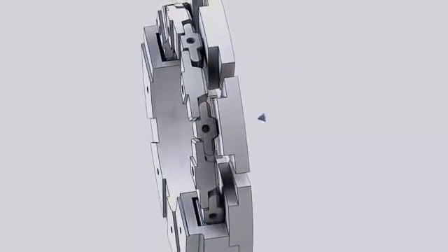The load transmitted by the thrust runner to a single pad causes the pad to press on the upper leveling plate right behind it. Each of the upper leveling plates in turn is supported by one edge of 2 lower leveling plates. The other edges of the lower leveling plates take part in supporting the adjacent upper leveling plate on either side. As a result of this arrangement, any excess of thrust load on a single pad is immediately shared through the leveling plates, so that all bearing pads will automatically receive equal loading.